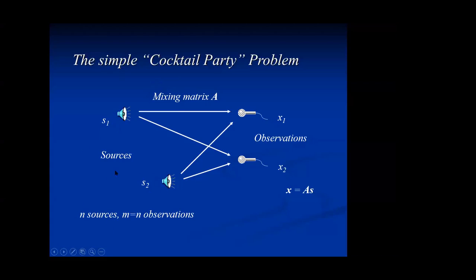So exactly in biomedical signal processing also, what is the problem? Here we have different sources. This is ECG signal. This is artifacts, motion artifact or any other artifacts. But here I have to observe these two signals. From this, I have to separate these two, the desired signal and non-desired signal. So for that, I have to know some information on S1 and S2. If I assume that these are independent, I can easily estimate this matrix, mixing matrix.